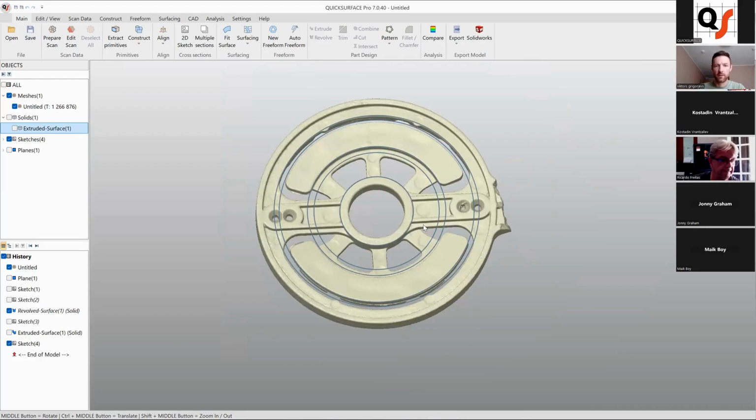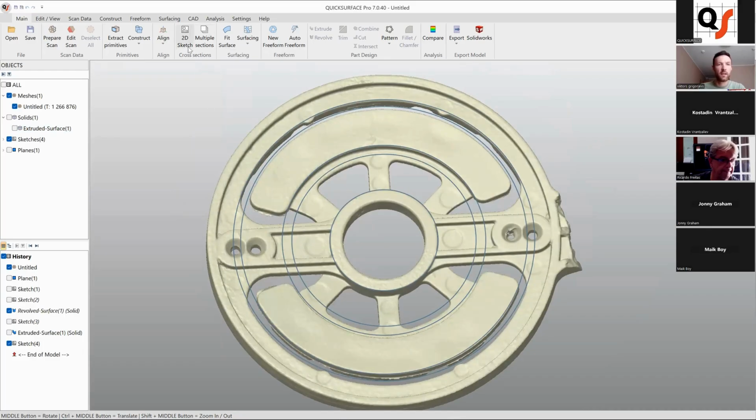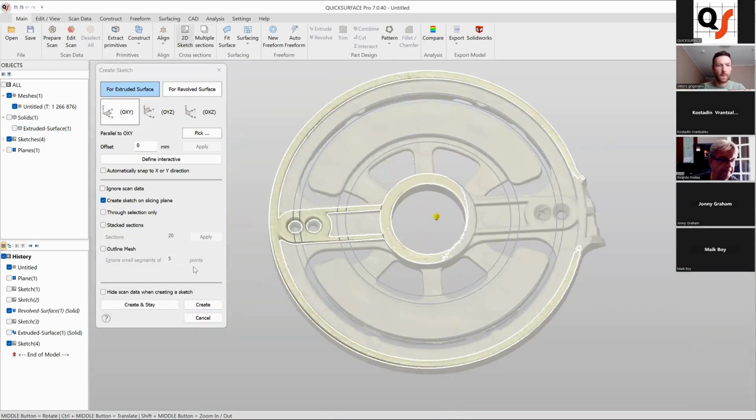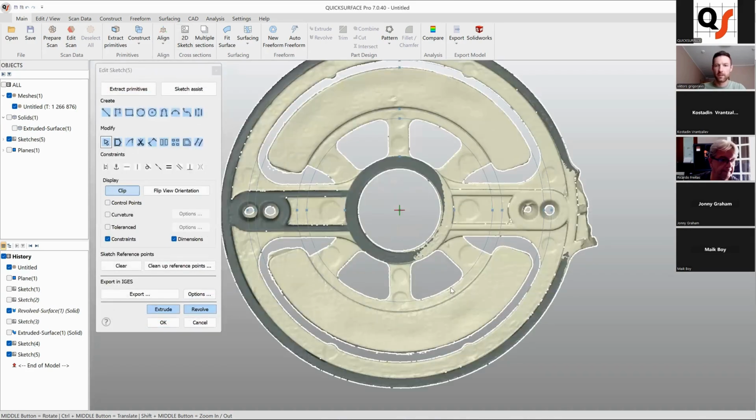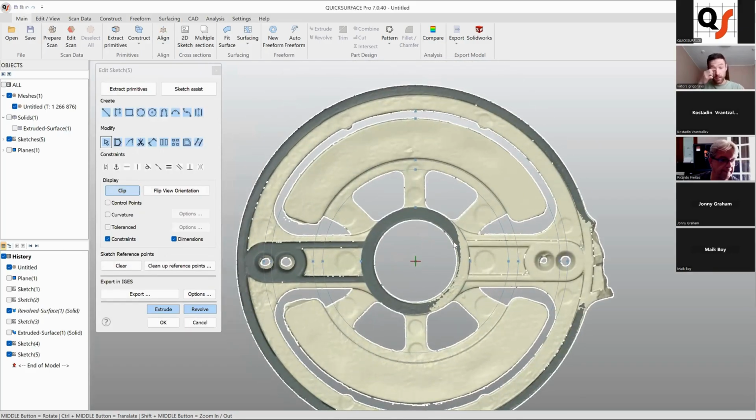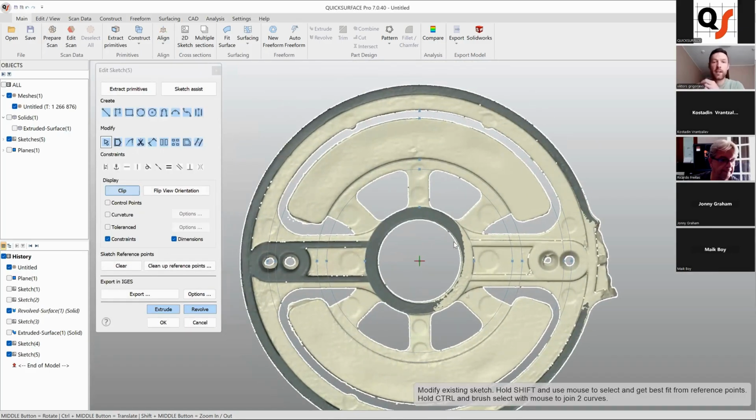So now I'm going to close this sketch and start another one. Again, I'm going to use outline mesh. The reason I created this reference sketch is to always select circles of absolutely the same radius, so we don't have different radii at every next step. So we don't have some steps or grooves on our model.